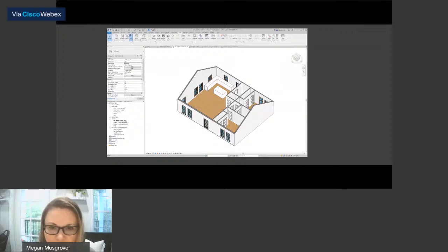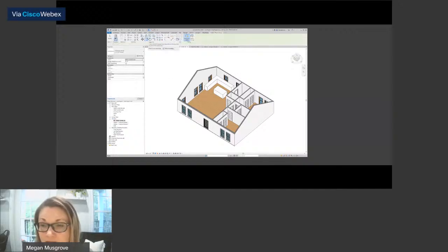So we've gone here. Okay. So we want to create a ceiling. I do not actually mess with these ceiling plans very much. I have kind of a different way that I do things. They're reflected ceiling views, and so they're like down looking up. What we're going to do is stay in this 3D view right here, and we're going to go to the architecture tab and ceiling, and it's going to give us some options here for the types. I'm going to do generic.